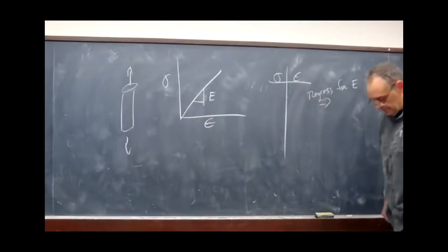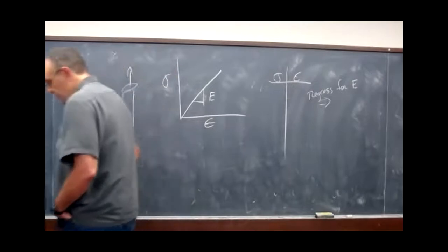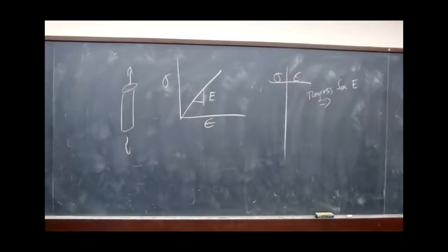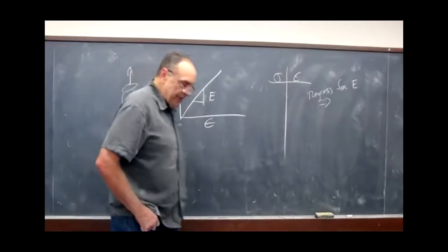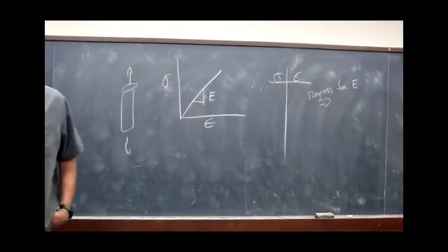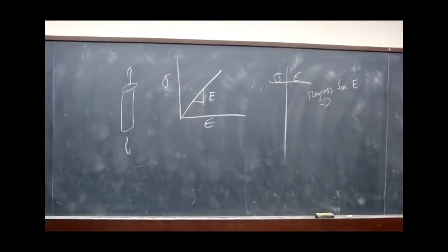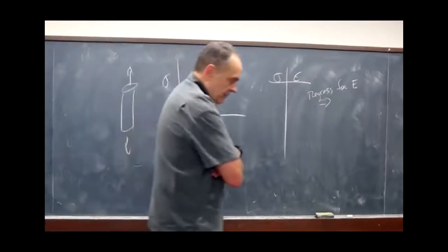And you need enough independent measurements, because depending upon your crystal class, you have multiple components. It's not E and nu anymore. So how would you go about measuring those in a diffraction experiment? Not trivial. And can you do it with a polycrystal? And what do you need to know?